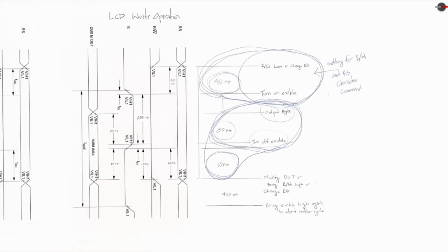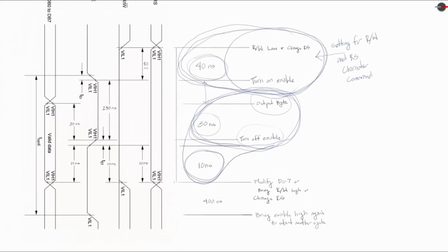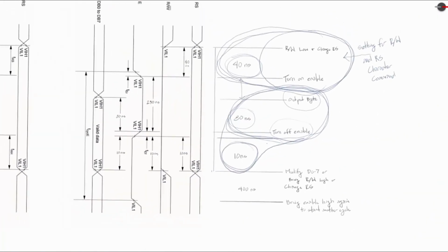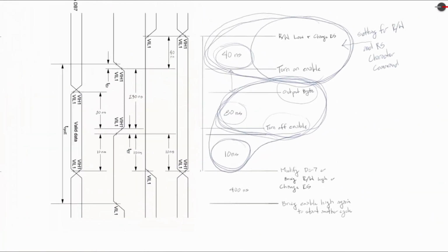At first, we're just going to have this stuff running really slow so we can see it on the LEDs. And then I'm inclined to hook it up to the LCD to output some commands and characters and see if it works with just a slightly faster speed, because all of these numbers are minimums. And that way we may not have to read it to check to see if the LCD is busy. And we'll go faster and faster to see at what point it breaks, if we get to that point.